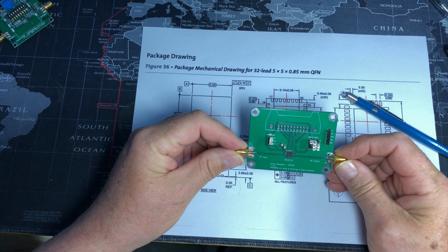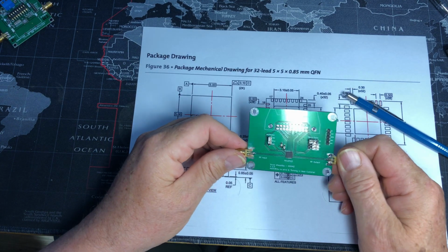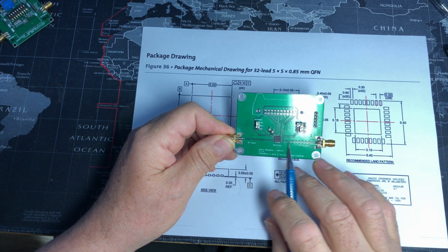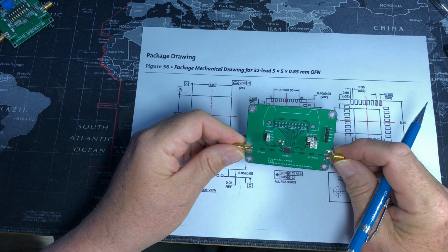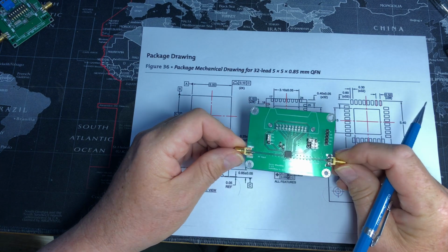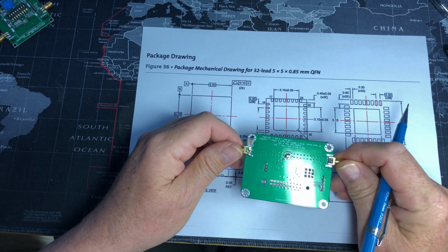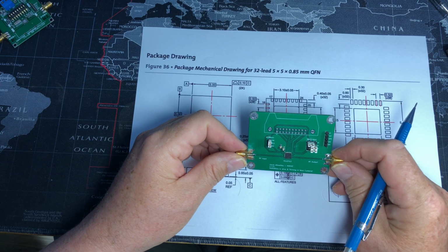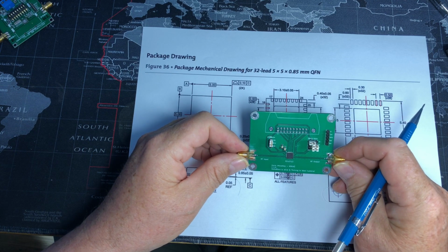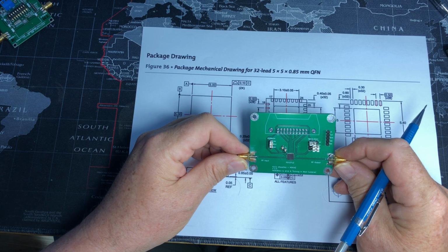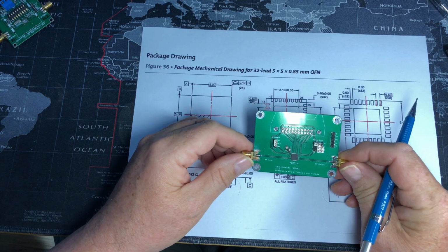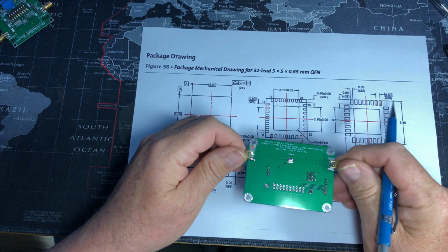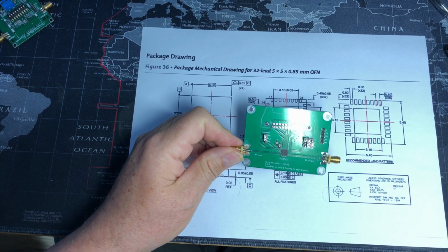best performance as possible. I ended up running to a 4-layer PCB, and I've maintained 50 ohm tracking between input and output. I've got a dedicated ground plane underneath, and everything seems to be fine. So that's my new breakout board. So the next challenge was to develop software to talk to this device from the Simple VFO hardware, and to test it. So that's what we're talking.